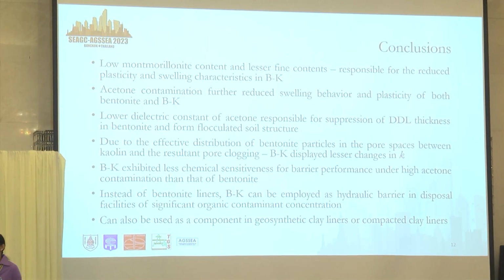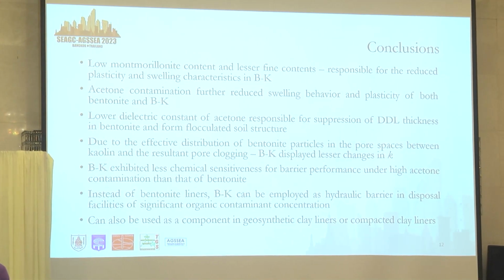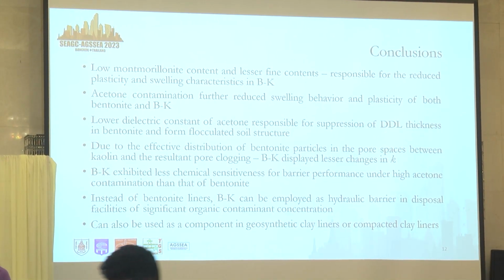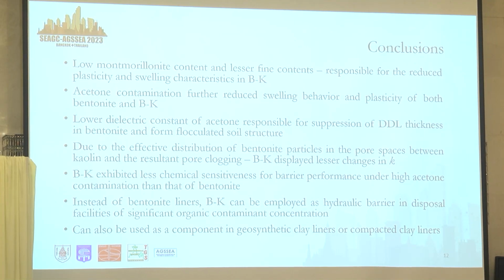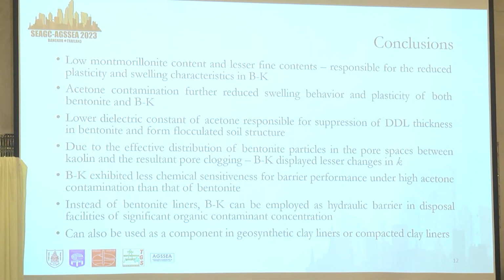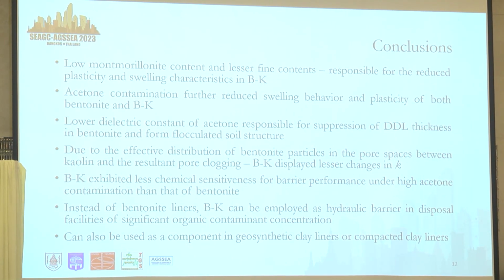And acetone contamination is changing the swelling behavior and plasticity behavior of both the materials. And the probable reason must be the lower dielectric constant of acetone. And BK displayed lesser changes in hydraulic conductivity, probably due to the effective distribution of bentonite particles in the pore spaces and the resultant pore clogging.